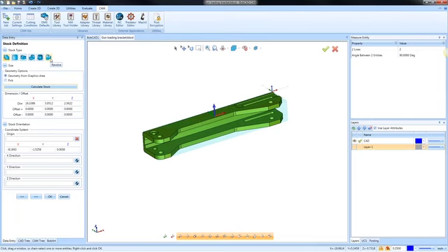If I was starting from a casting and I wanted to use the casting shape as a stock boundary, then I would probably use solid or STL, one of these two options as my stock, and then I would select it. Okay. But let's not get sidetracked here. We have our stock set at rectangular. We click calculate stock. We could add offsets here to add additional stock. I'm not concerned with that right at this time.